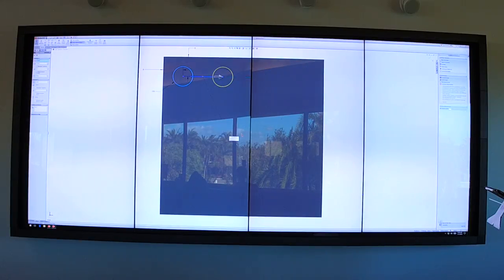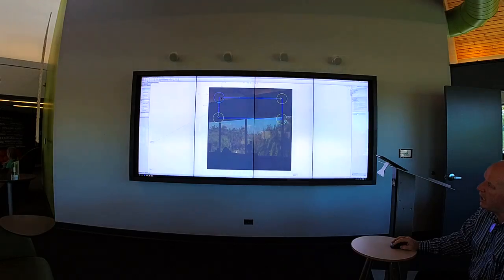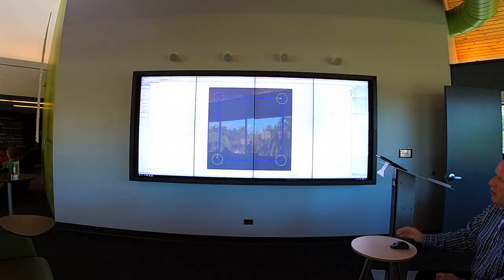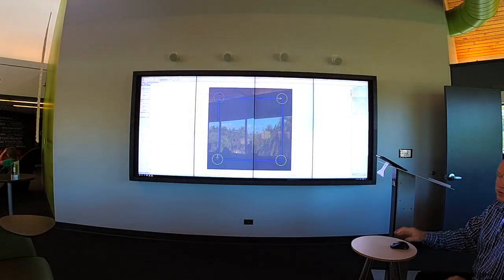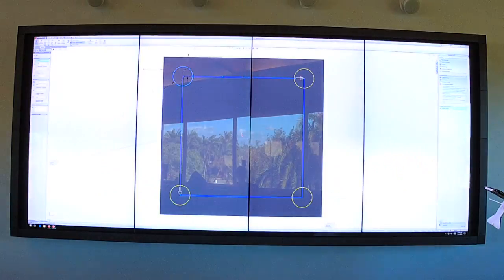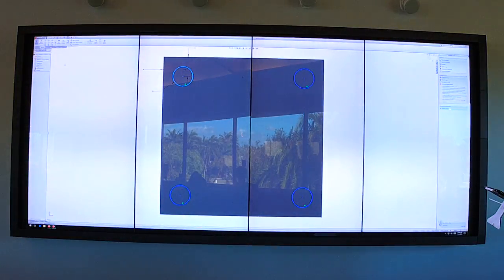And I can increase the size here where we're at. So that's giving me approximately the right size there. I want 4 on the bottom, so I'm going to add a second row. Now you've got an option here to invert the direction. So if I invert the direction, and again I bring this down, I've now got a series of 4 holes. So I'm going to click OK. So what I've done there is created, I've created a linear pattern.